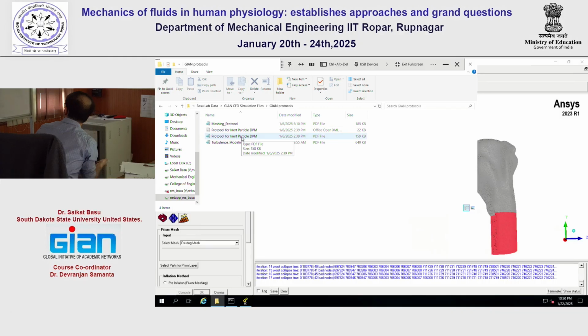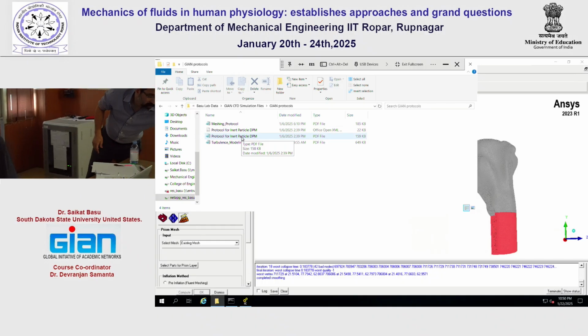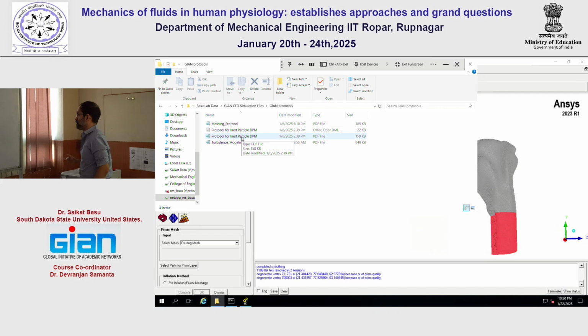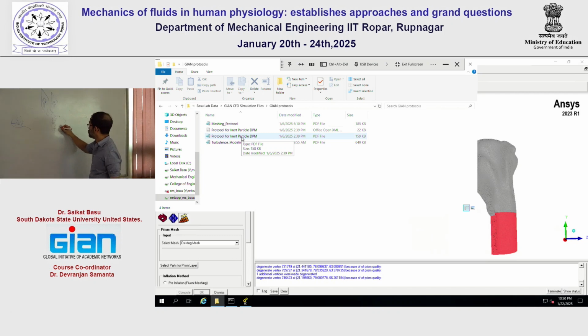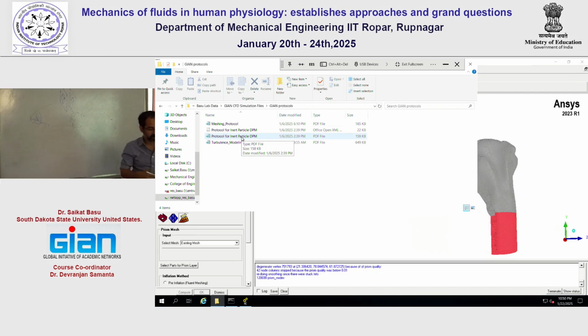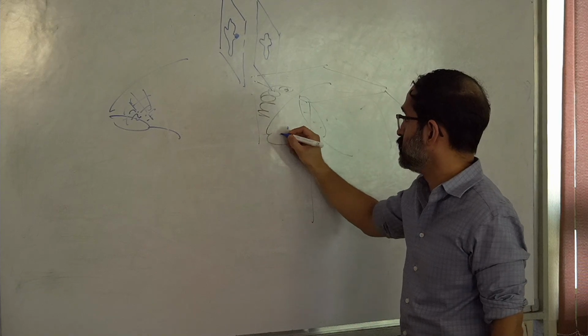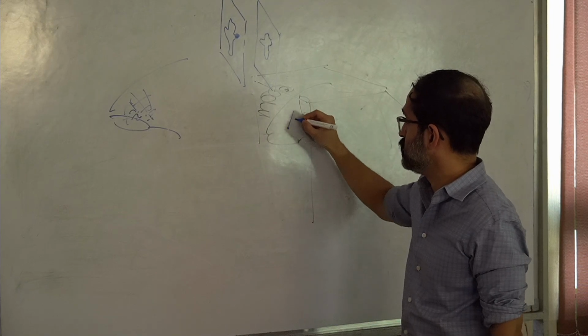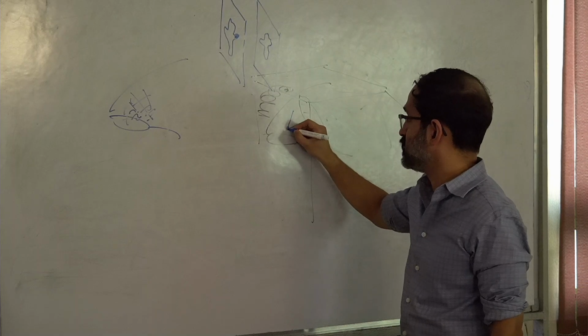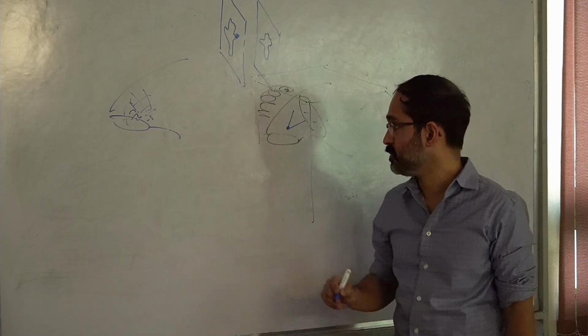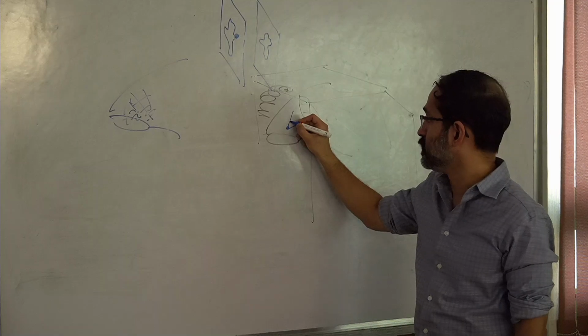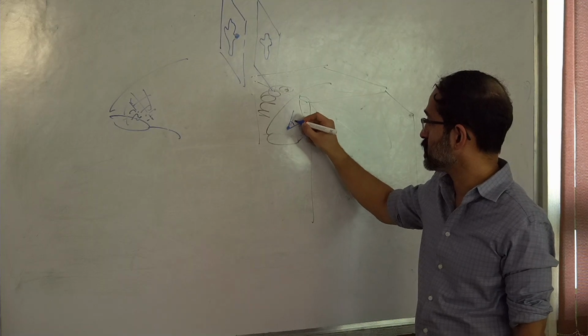For the drug delivery application, the particles are going to go into the airspace in a conical shape. So there we need to figure out a point where the spray nozzle is located, then identify the coordinates of that point and set it up. We need to know what this angle is, and then the particles go out like this.